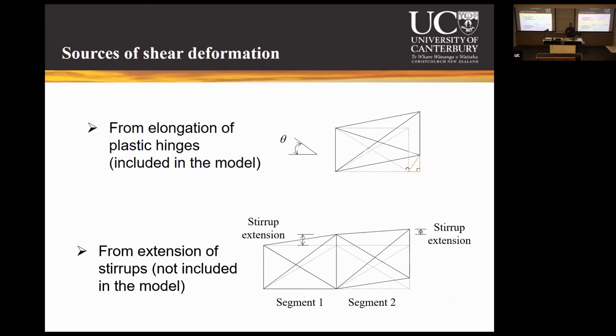Right? So when you apply cyclic loading to a ductile member in the plastic hinge region, it might be difficult to comprehend at the beginning, but the depth grows, because the confining action and anti-buckling action of the reinforcement stirrups actually cause some of the stirrups to yield. And it was not easy to actually get evidence of that.